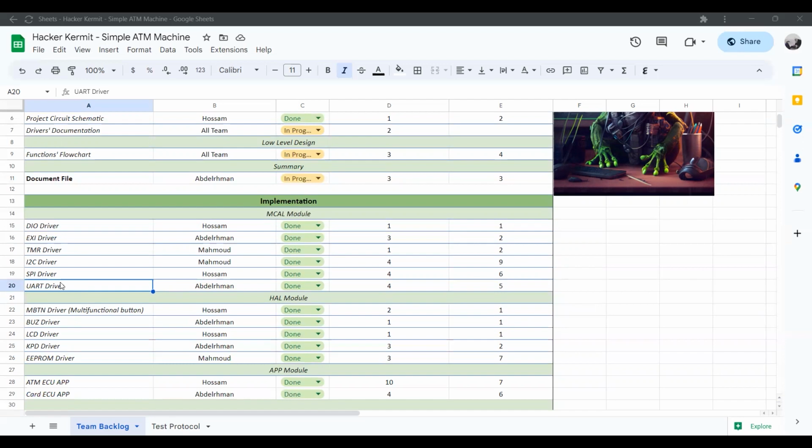That wasn't the case while implementing the receive byte API. Why? Because this specific API needs to poll until receiving a byte, and implementing a timeout mechanism would cause a corruption in the string received during receiving the string.